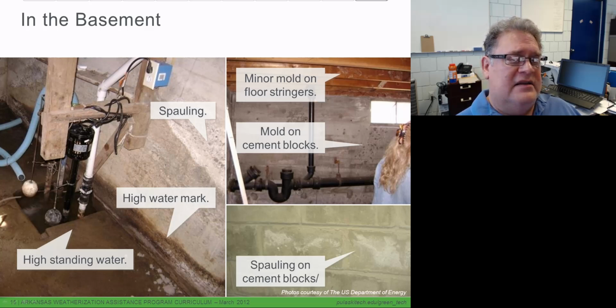That can allow evaporation. That evaporation is going to put moisture into the block, and if that moisture condenses and freezes, it's going to create the problem that we're having over here, which is spalling. Spalling is a term for concrete, stone, brick, or block being blown out, chunks of it being broken off from frozen water. And if you don't have the proper type of brick or block, like on a walkway, you'll see the walkway damaged from it.